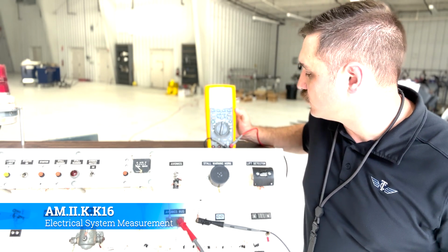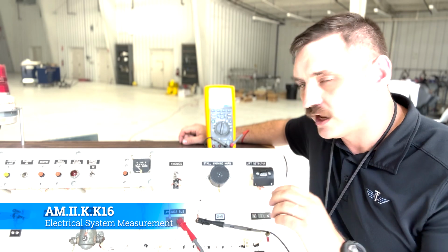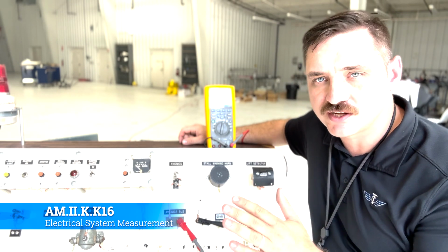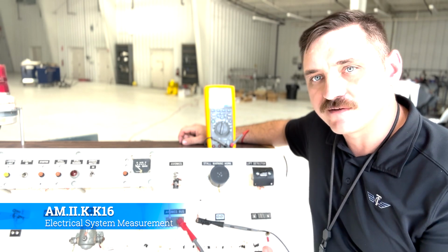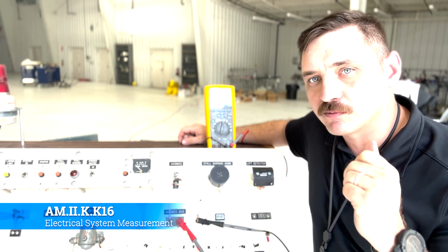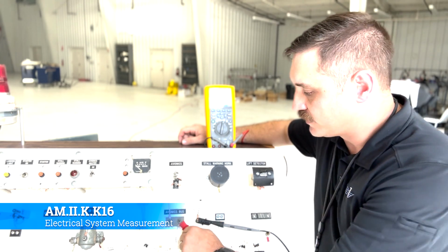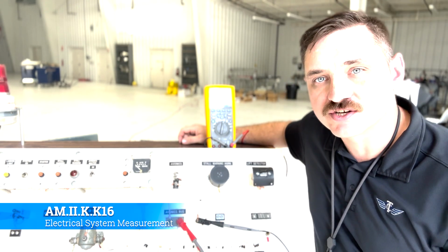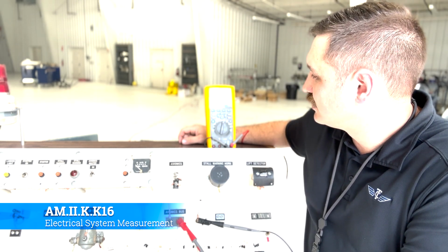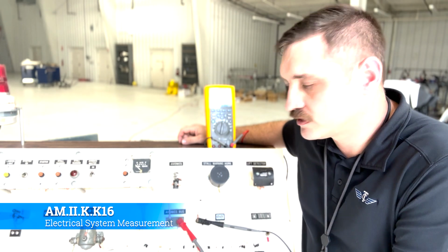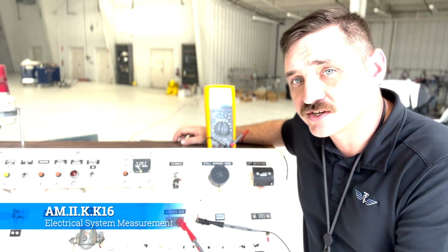All right, so it's a good learning moment: don't just take your first check for granted. Shoot through the wire, and if it's ringing, try to see if you can disrupt it on purpose and then put it back. Even if it's just taking the lead away and then putting the lead back on to determine that you're actually getting continuity. So right now we're reading about 160 ohms or so, and so we know that we're getting continuity through there. So now let's check power.